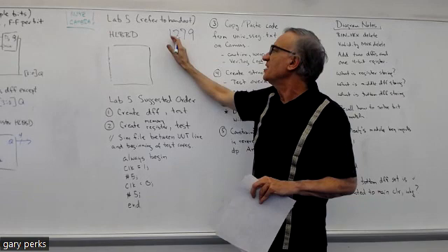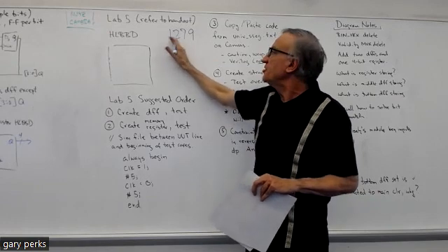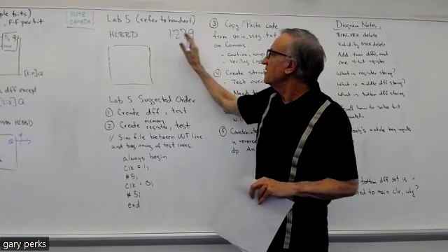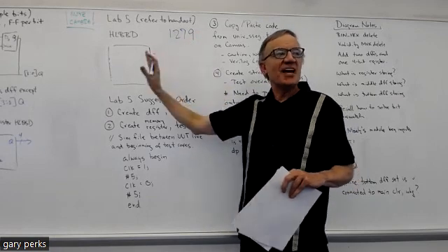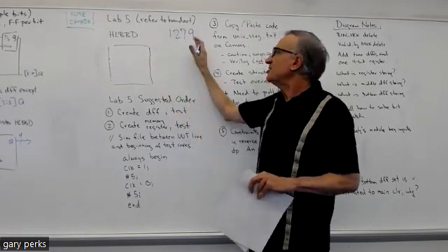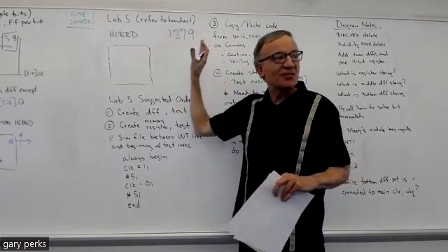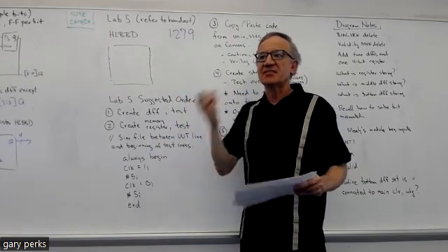third to the left display. And then sometime later, it'll display the 1. And then it just keeps doing this, right? It displays the 9 here, the 7 here, the 2 there, the 1 there, and it goes back 9, 7, 2. And it just keeps doing this. But it does it at such a fast rate that our eyes don't detect that it's going 9, 7, 2, 1. We just see a steady number. Okay, so that's what time multiplexing is.